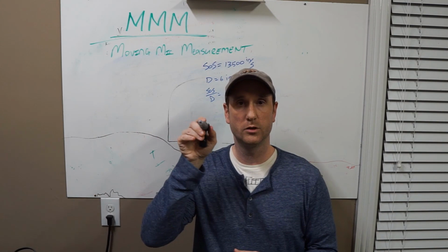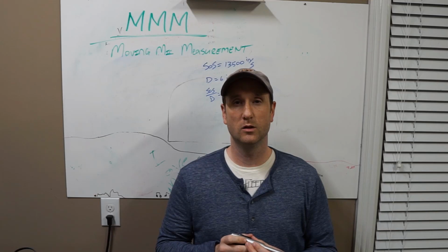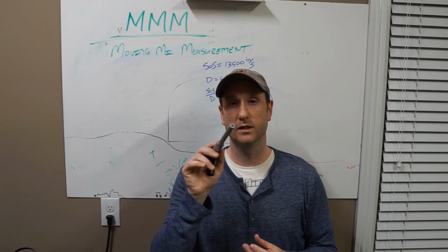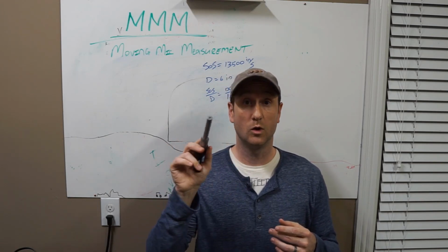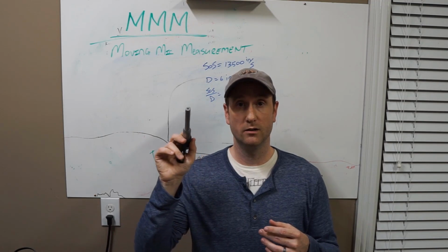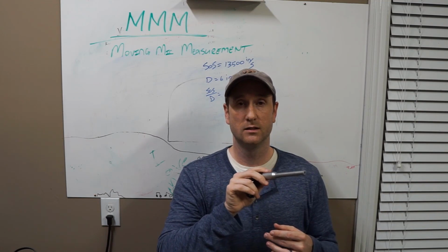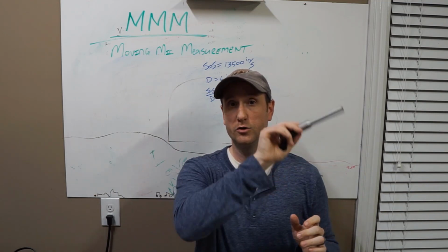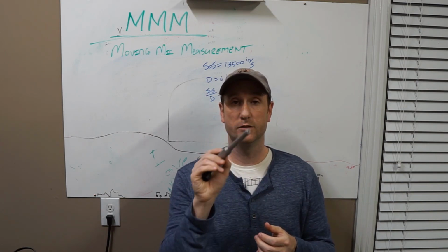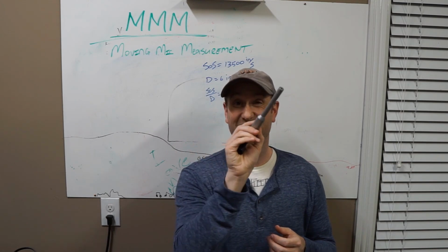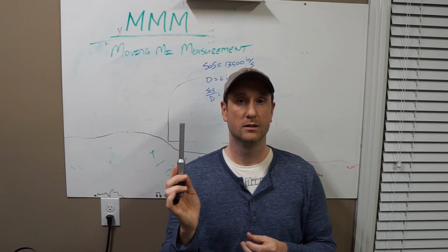The issue with doing measurements in space and then averaging them together is the response is only as accurate as the number of data points that you measure and then average together. So instead of having an infinite number or a quasi-infinite number of measurements, you have a select few. Let's say most people will do 1, 2, 3, 4, 5, 6, and it may not be in this small window, they may do a larger window. Once you average those together, the data is only as good as each individual point. You're missing points in between. Now, the moving microphone method aims to fix that.